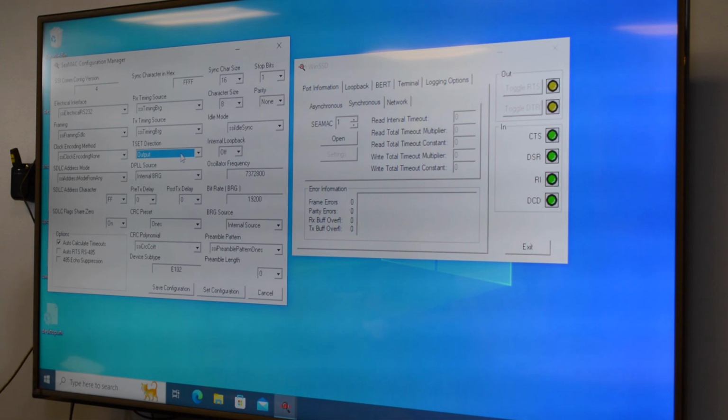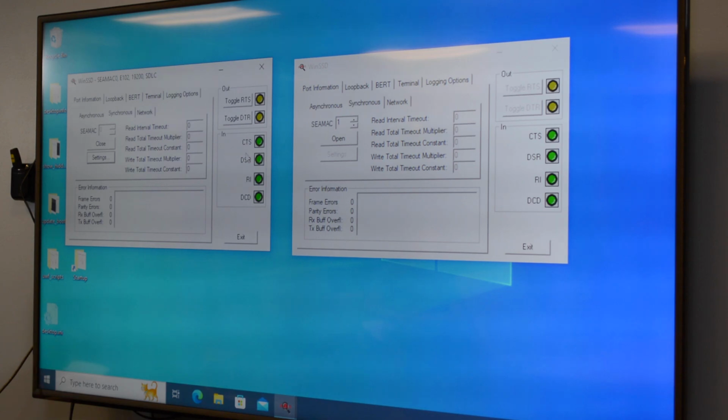I think it's pin 17. I think that from pin 24 on the bottom card, that will indicate to it when to sample the bits. I'll turn CRCs off because if you have a CRC error, you lose the data and it's harder to troubleshoot. And I'll use synchronous idle. And I'll put in a timeout of 300 milliseconds.